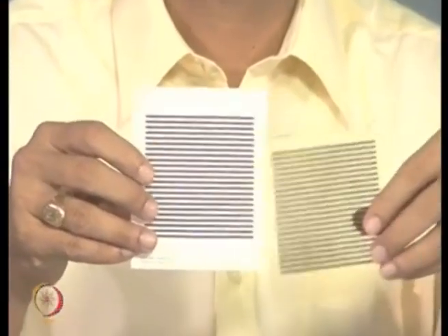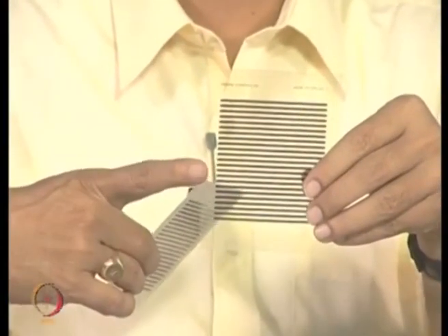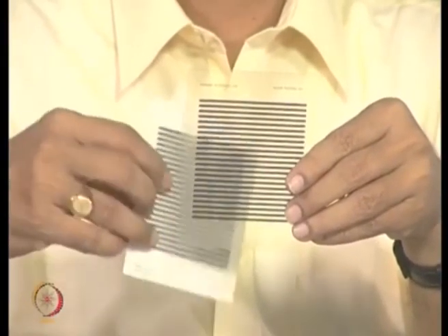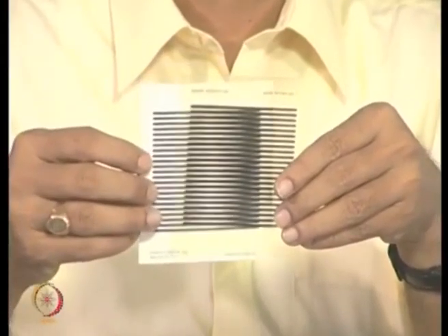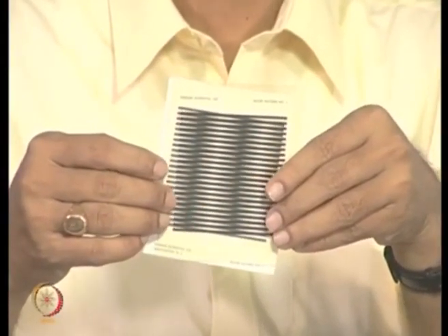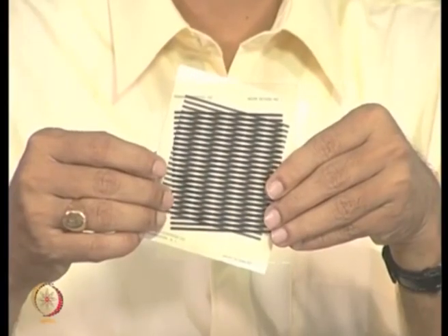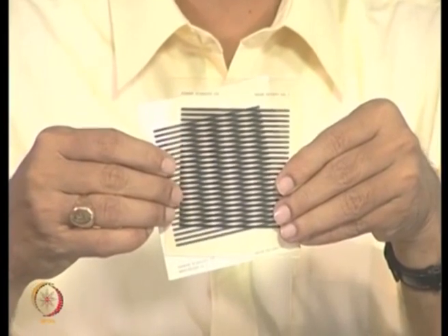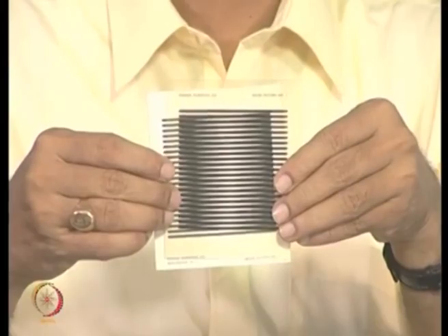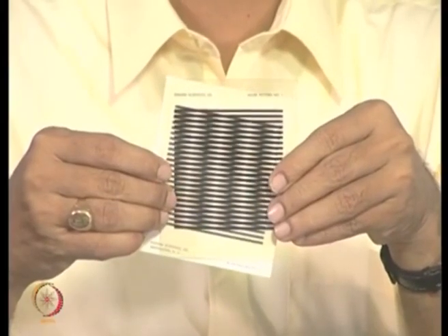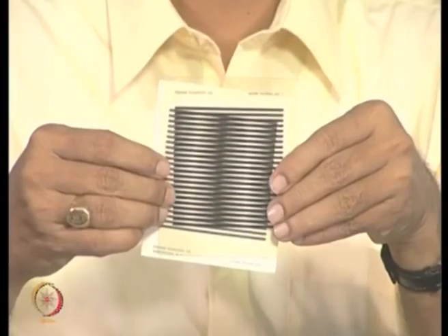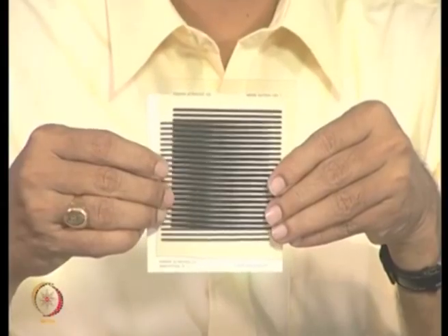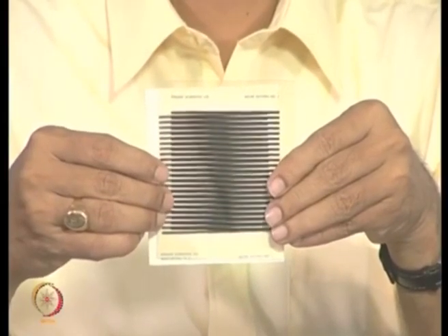And what you have here is the grating, this is the grating here, and this is nothing but horizontal bars here. And when I put another grating which is very similar, you see beautiful fringes when I rotate them relatively. So, what you have here is, it is by mechanical interference you see these fringes. Moiré is not an optical interferometry technique, it is a mechanical interference of the grids, that is what you get. So, I get this when I rotate it relative to the other, I also get it when I translate it with respect to the other.